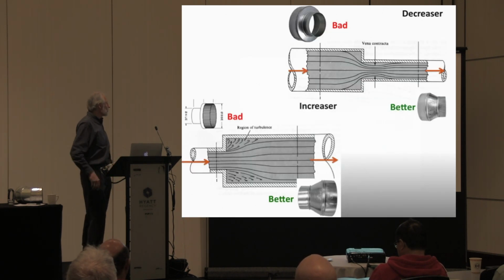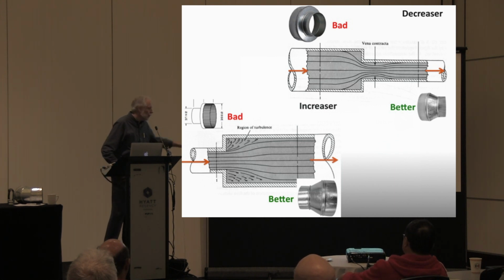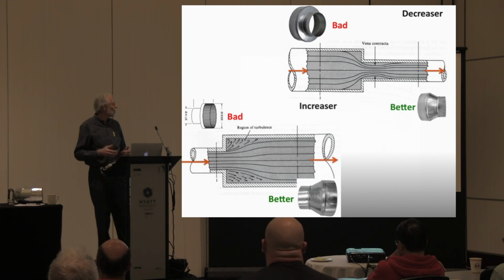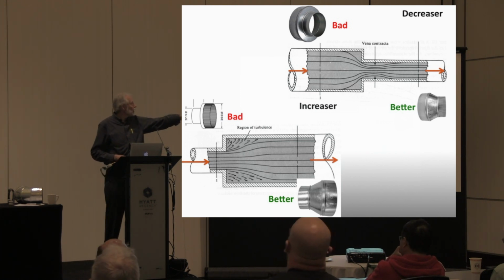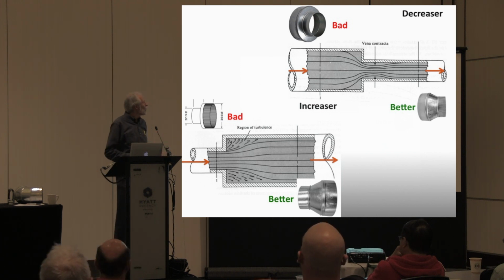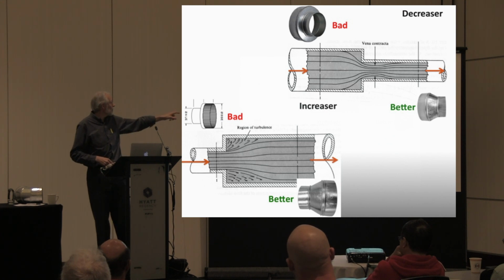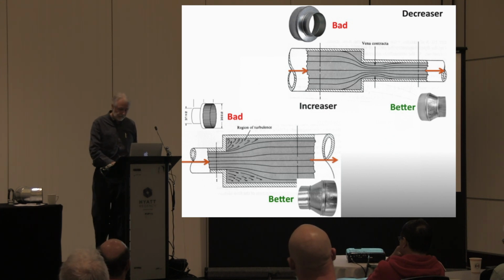This goes on a lot in our business. People think this doesn't cost them at all when you put small duct into a big duct with a step. Huge pressure losses doing that, although it's not intuitive that that would occur. There's a bit of a recognition that the reducer will cause a restriction, but they're both equally damaging. We should be using tapers instead of sharp throat fittings.